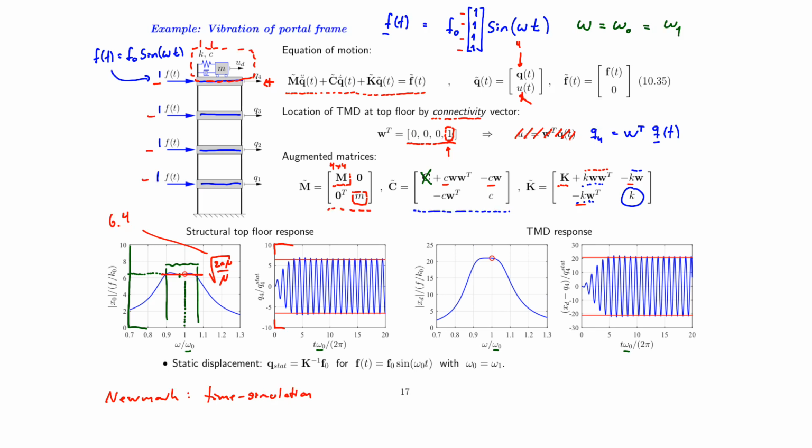And you can see in the beginning I have an increasing resonant build-up. I have a slight overshoot here, but basically I end up at my steady state amplitude quite fast, because I have fairly much damping in my system because of the TMD. Now my response is plotted for the top floor. So Q4 is equal to the top floor.